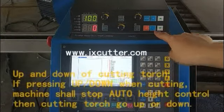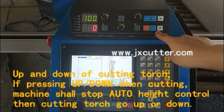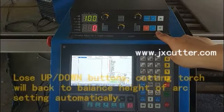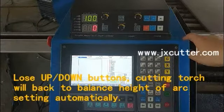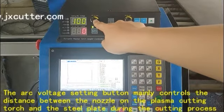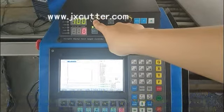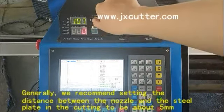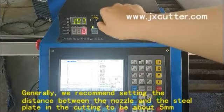Up and down of cutting torch. If pressing up/down when cutting, the machine shall stop auto height control, then the cutting torch goes up or down. Lose the up/down buttons, and the cutting torch will go back to the balance height. The arc voltage setting button mainly controls the distance between the nozzle on the plasma cutting torch and the steel plate during the cutting process. The number can be adjusted. Generally, we recommend setting the distance between the nozzle and the steel plate in cutting to be about 5 mm.